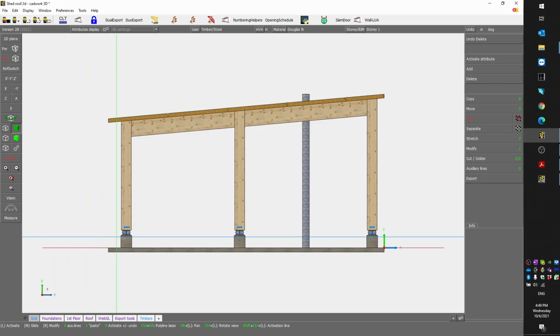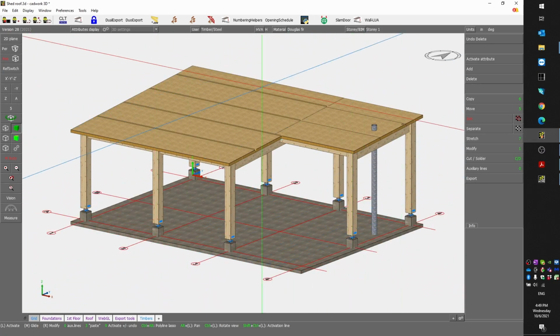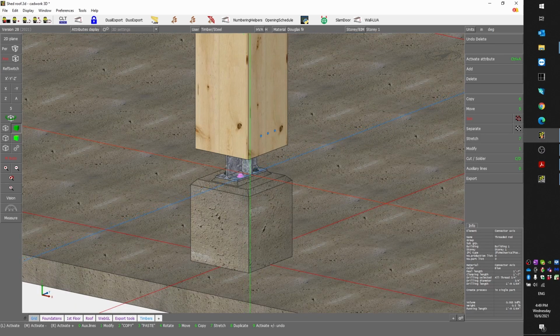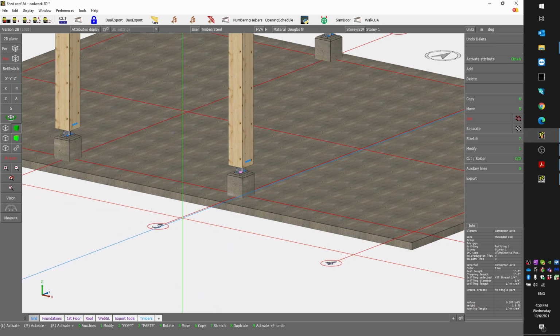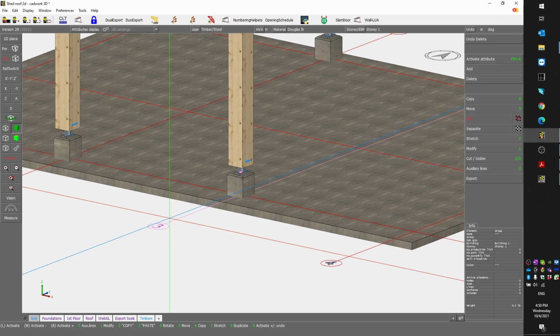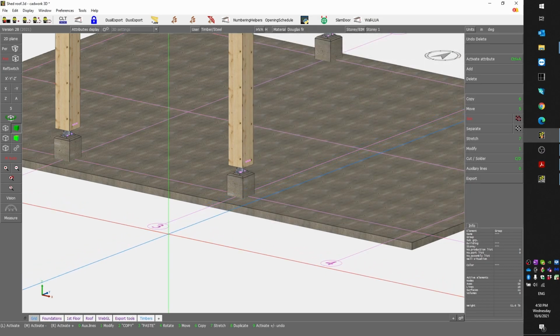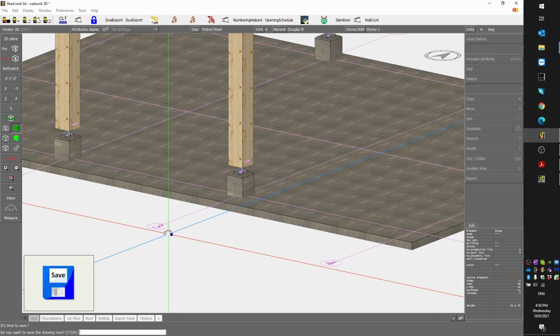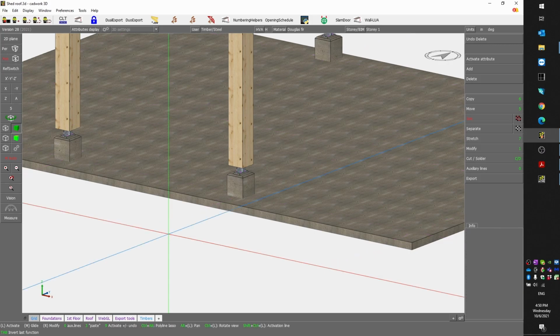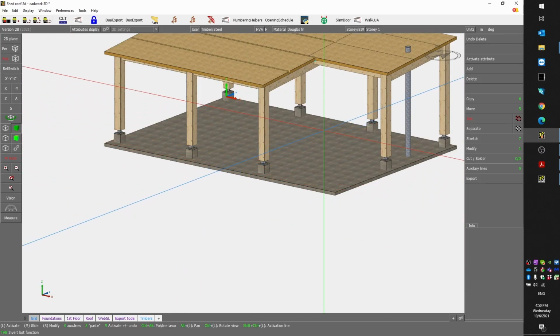So once it's done, let's go in a view. Let's do an X view. And here I'm gonna extract different views and it's more like a global view of our model. So I don't really need all the bells and whistles. I'm gonna hide these connector axes and eventually even the grid lines. So I do Control A and then T for type, and I can press the multiplication button or the star on the numpad in order to hide these guys.